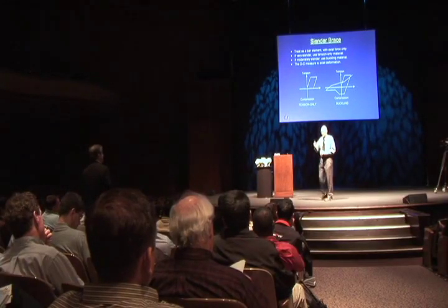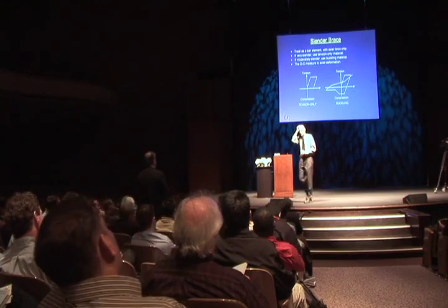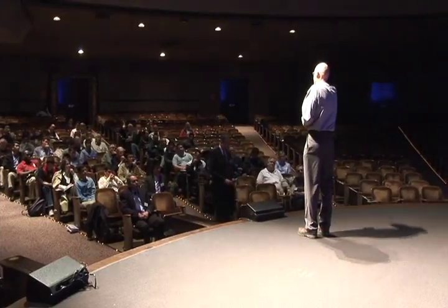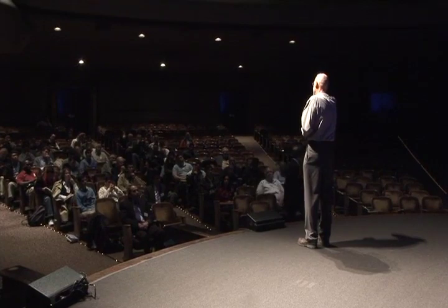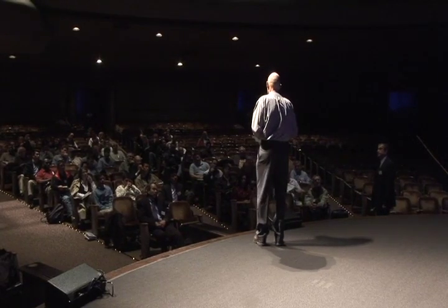Well, I will talk about floor diaphragms a little bit, and shear walls. If it's not okay to assume a rigid diaphragm and you have to model it as deformable, then you've got to model it using elements. That's not an easy thing to do, and it does also increase the computer time rather dramatically, unfortunately. It can be done. Perform has quite a number of elements that you could use to model deformable diaphragms. I'll say a little bit about it when we're talking about shear walls.